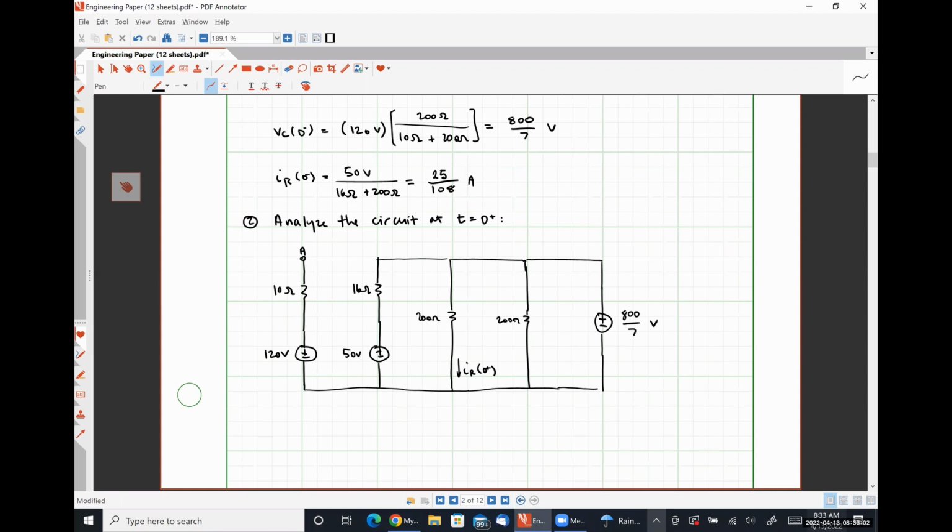So current division requires us to know a known amount of current flowing into a parallel network. Since we don't have any current sources, we probably don't have any known current. We could, but that's too much work. You're 100% correct that we could do a source transformation on the left-hand side because we do have a practical voltage source. Let me ask you guys a question.